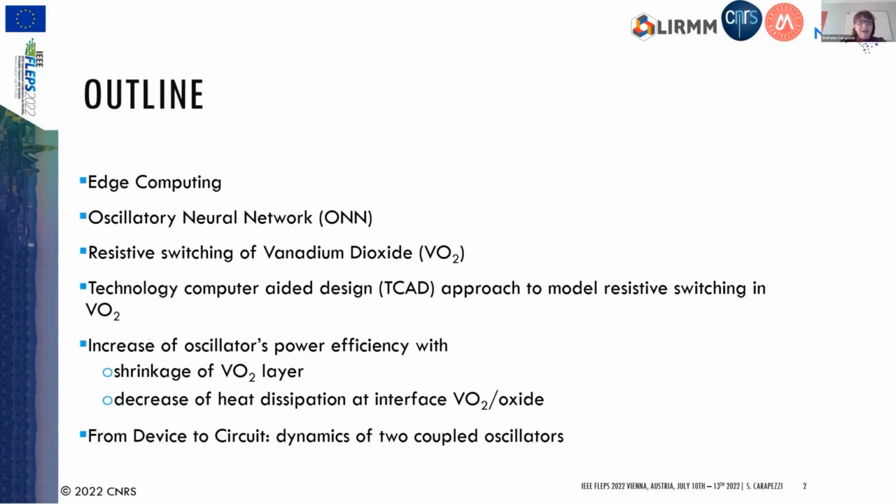And my work, as I mentioned before, is in particular about simulation. So I will show how a TCAD approach, technology computer-aided design approach, has been implemented in order to model this resistive switching of vanadium dioxide. Now, TCAD is a common technique that has been used in the semiconductor industry and has already been very successful in assisting the development of silicon technology. And it's becoming more and more important now because the technology is dealing with materials with exotic properties, so unconventional materials compared to silicon, and also new device concepts.